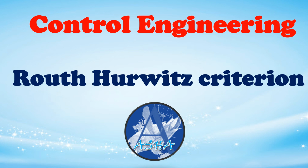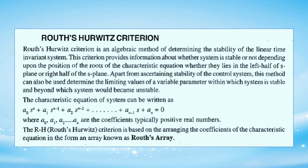In this session, I will be discussing the Routh-Hurwitz criterion, also known as the RH criterion. Routh-Hurwitz criterion is an algebraic method of determining the stability of a linear time invariant system. This RH criterion provides information about whether the system is stable or not, depending on the position of the roots of the characteristic equation, whether they lie in the left half of the S-plane or the right half of the S-plane.